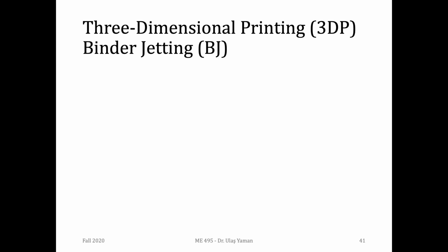What are the software challenges during the completion of the additive manufacturing side? When we transfer the file to CAM software, we need to use AMF, or we need to use other proper applications in the CAM software. We don't have any specific requirement for these processes. The fundamentals are the same, and the same pipeline is followed. You obtain the STL file or different file formats, import into their CAM software, do a little setting, and then print.